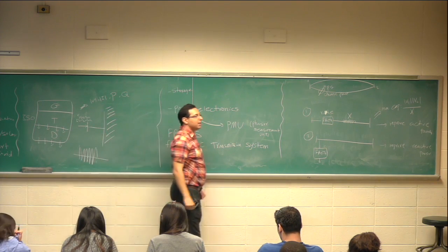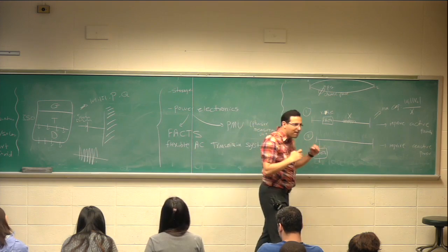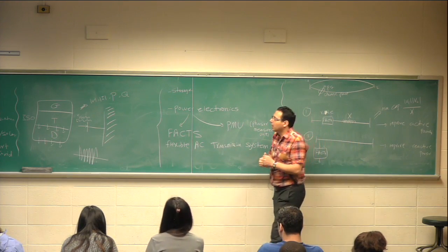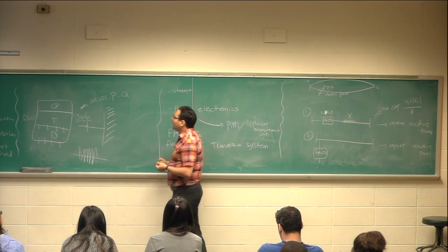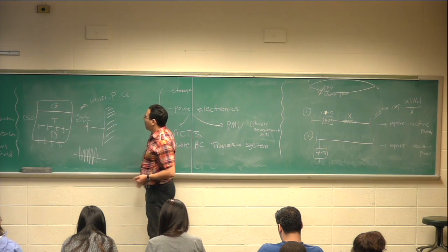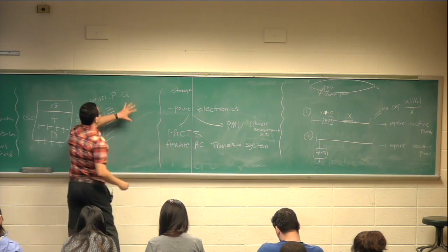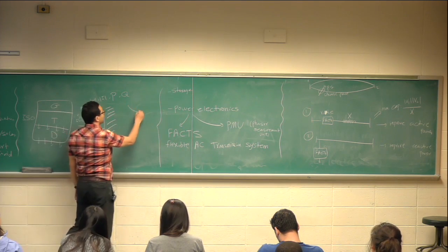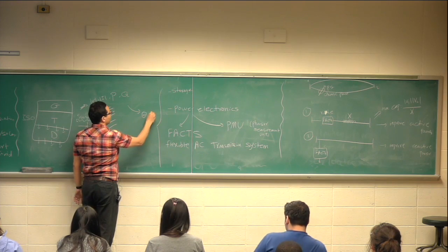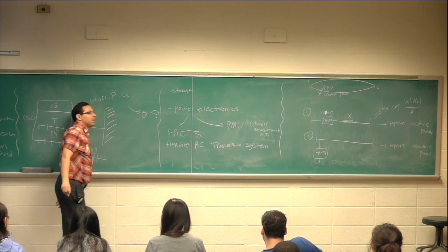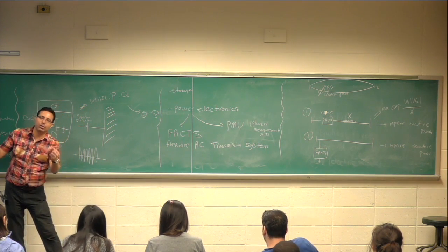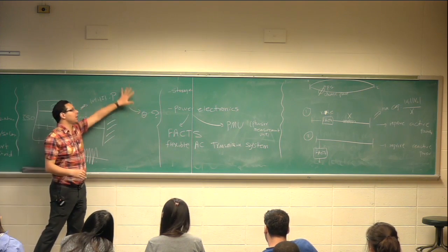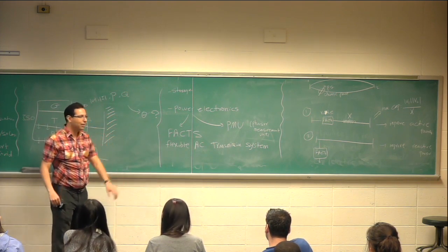Traditionally, they measure parameters that change slowly, like voltage magnitude, current magnitude, active power, reactive power. Then from this, at this point and the rest of the world, they have to deduce angles. This is like a power flow equation. We said it's very hard to deal with this. There are convergence issues for Newton, and this was a nightmare for power people.